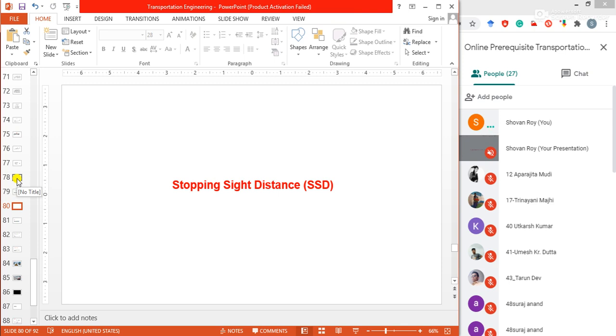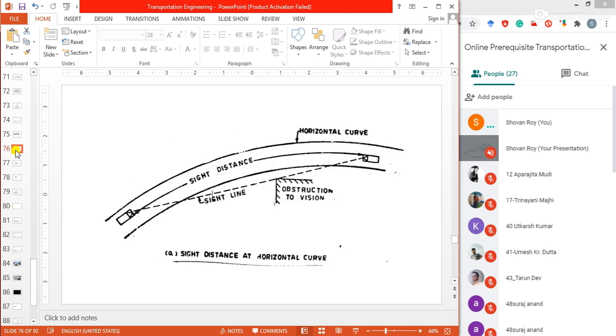Okay. So three sight distances are considered, already told by me, and the standards for sight distance should satisfy the following three conditions: the driver traveling at the design speed has sufficient sight distance or length of road visible ahead to stop the vehicle in case of any obstruction on the road ahead without collision.